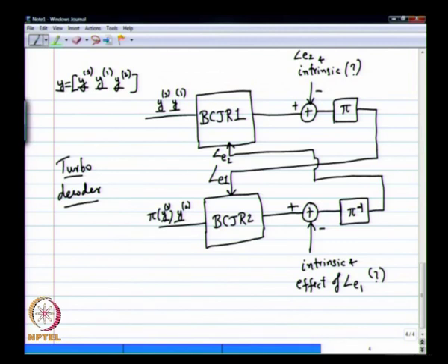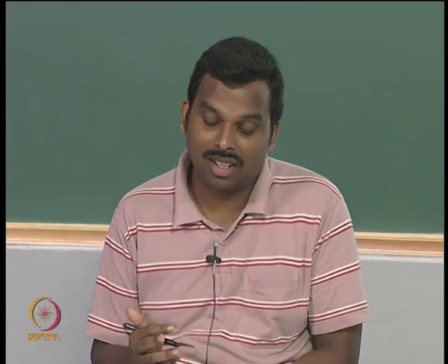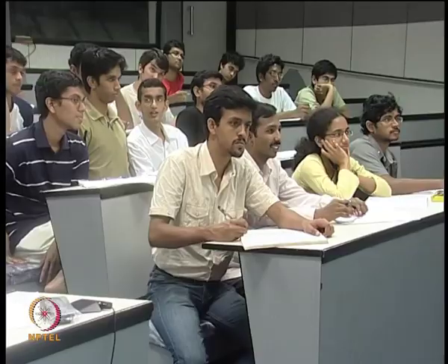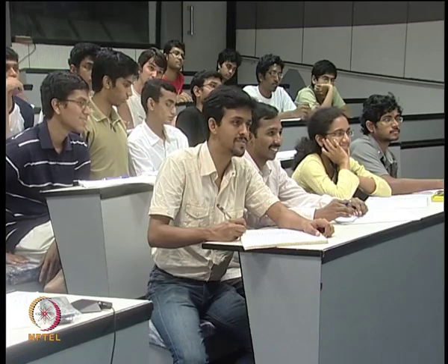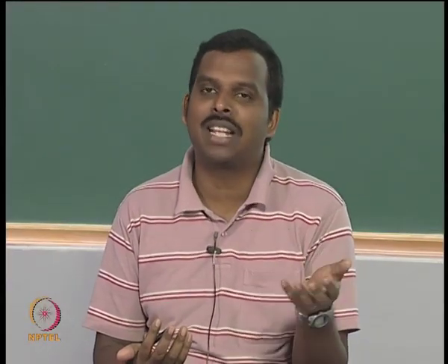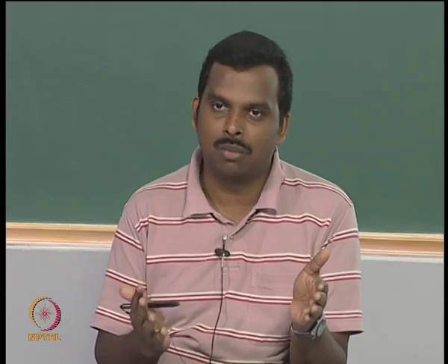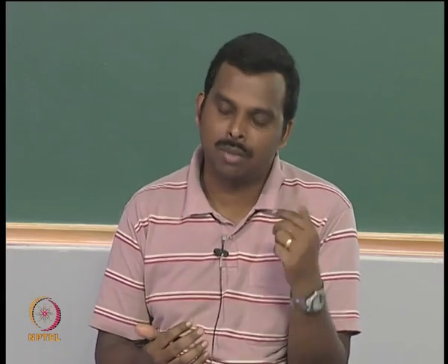Yeah, I mean, so there are several rules you can use. Some people are suggesting that LLRs, once they become sufficiently high, they may not be all high. You know, some LLRs might refuse to become high. And what do you do? So, for instance, the usual rule that's used is after 5 times or 10 times you stop. So that's the most implementable rule, because that's what you can implement in a system. After so many iterations, after taking so many clocks, you have to stop and say what it is. Okay, so that's something you can do.